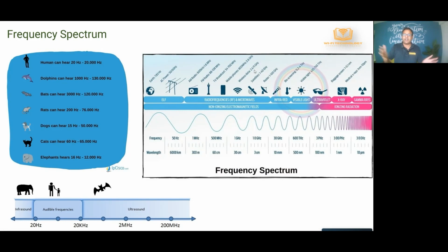Within that range, you have a list of unlicensed frequencies that are available and actually used for Wi-Fi transmissions. Some of these frequencies are opened up for unlicensed use. As I mentioned in one of the sessions before, the government lets people use those frequencies as long as they meet certain requirements. They allow them to use them without paying anything. It's free for people to use those frequencies. So Wi-Fi operates in that spectrum, between around the 2 gigahertz range to the 7 gigahertz range approximately.